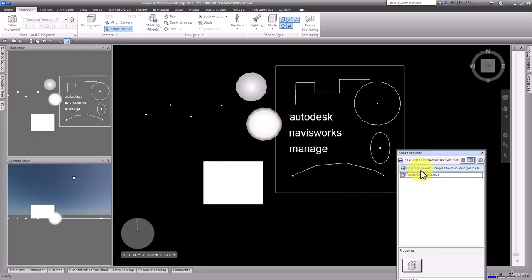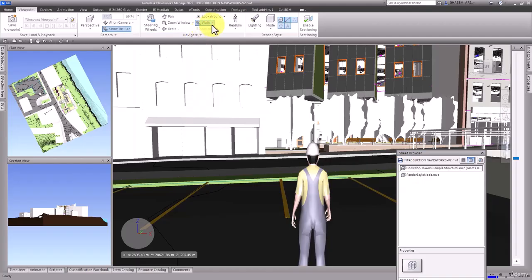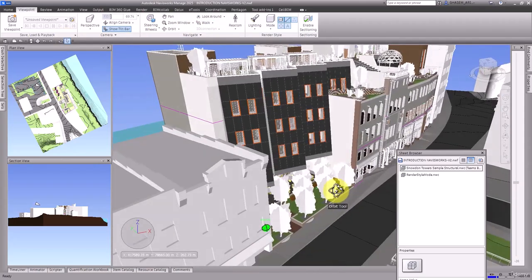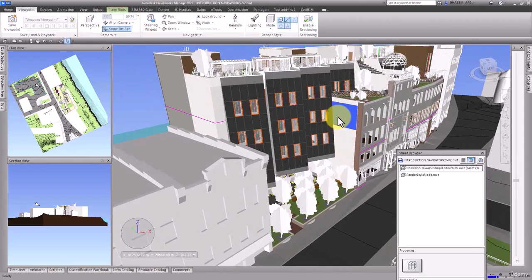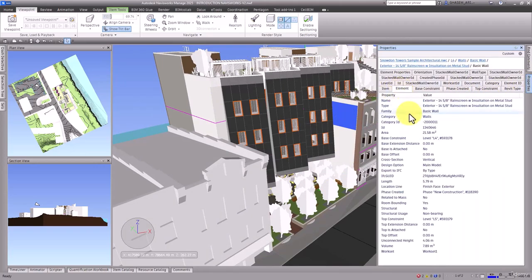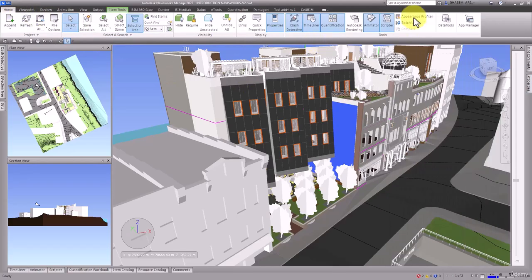The next point: during the work we might use different options to set the colors or change them. I'm just giving you examples. Let me select this wall, go to the properties window, go to element, for example, and click on all types of this wall. Let's click on find matching item, and after that set a color for it.